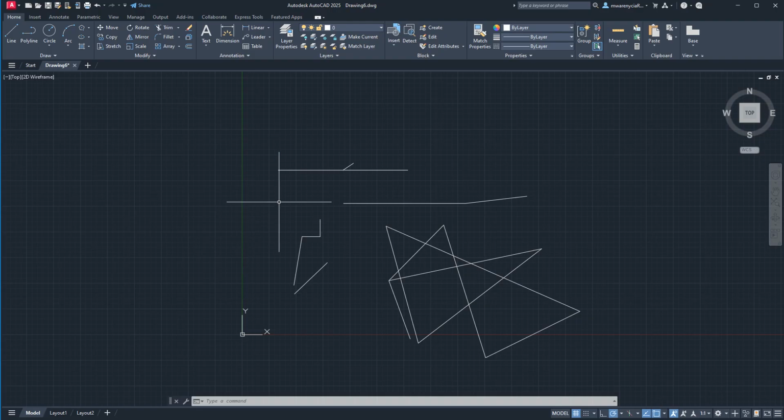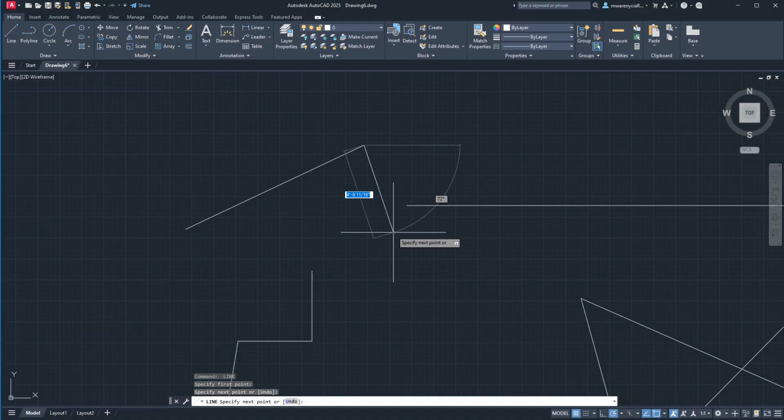Sometimes you want to pause a tool, and when I'm using AutoCAD, I've got my right hand on the mouse, and I'm resting my left hand over the left side of the keyboard. So I've got one finger near the escape, and one near the space bar. The reason why I keep my thumb on the space bar at all times is because you can repeat the last thing you did with the space bar. So I just did a line tool right there. If I hit space bar, it brings up the line tool again, and I can click through.